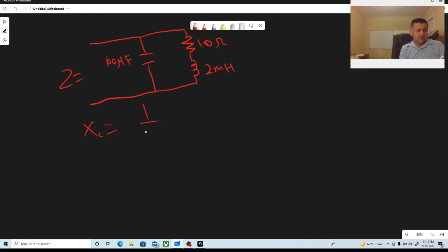So, if you take 2 pi and you multiply that by 60 hertz, it's about 377. Remember that this is omega. Omega is technically 2 pi f.